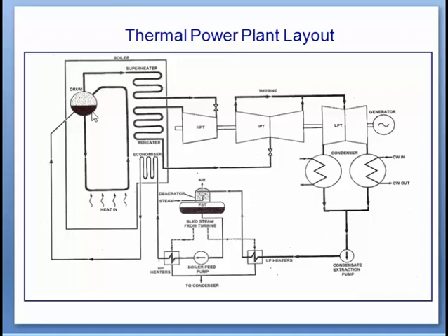So the purpose of the boiler drum is to separate the water and vapor mixture because of density difference. The vapor takes the upper space and water again through downcomers comes to the bottom ring header, and through it goes to the riser tubes. Because these downcomers are positioned in the non-heated zone and riser tubes are in the heated zone, because of the density difference, natural circulation of water takes place.